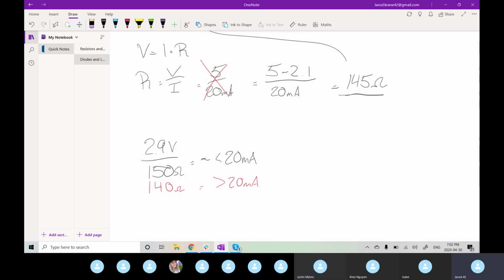But you'll be able to run through the calculation again saying, okay, so this is the minimum. Maybe I want to do 170 now, 170 ohms. See how that acts. You'll see the current through the LED will drop, which makes it so brightness goes down.